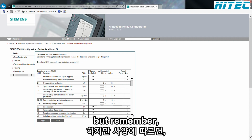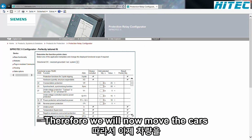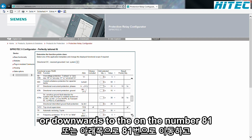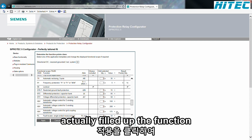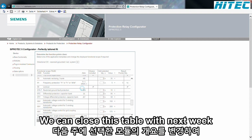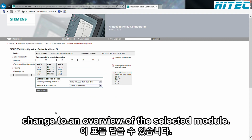But remember, according to the specification, the device should contain frequency protection. Therefore, we will now move the cursor downwards to the ANSI number 81 and select the frequency protection function once. The total of function points is now 50, which exactly fills up the function point class. With a click on Apply, we can close this table. With Next, we change to an overview of the selected modules.